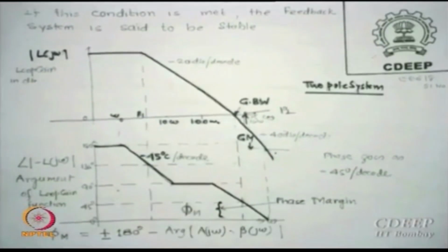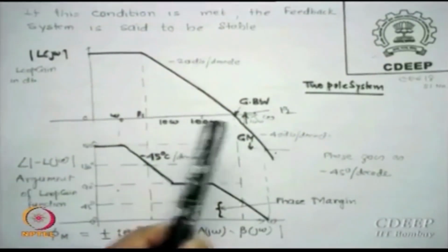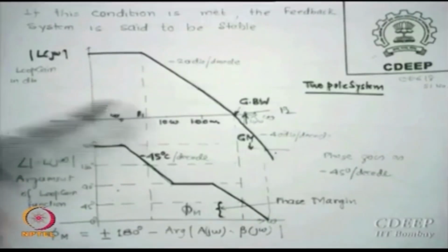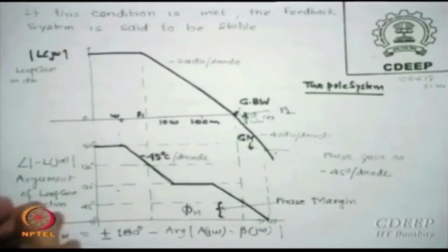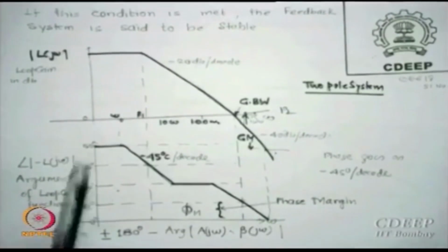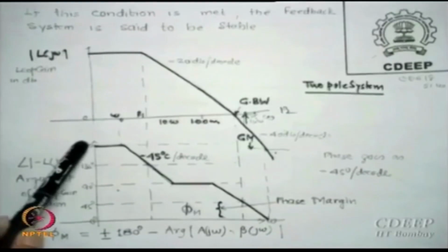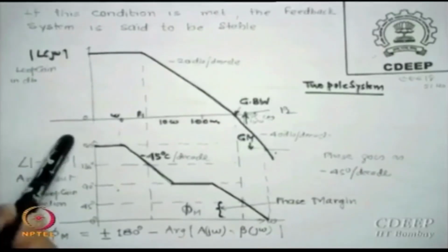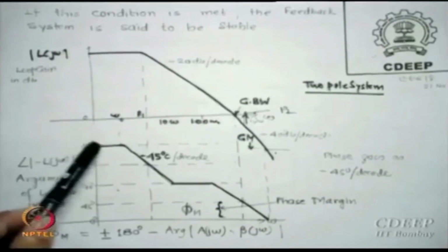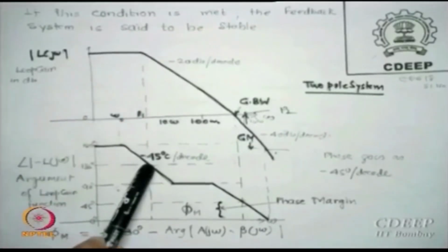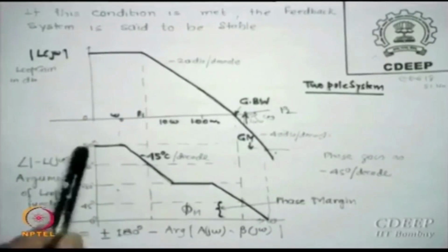Then the fall will be minus 40 dB per decade, 20 from this, 20 from the other, and if you now plot this in the case of phase values, at every pole we know 45 degrees should show. Since it is shown from minus of this, I am starting from 180. So somewhere at the pole it must go 45 degrees down from this maximum value 180.